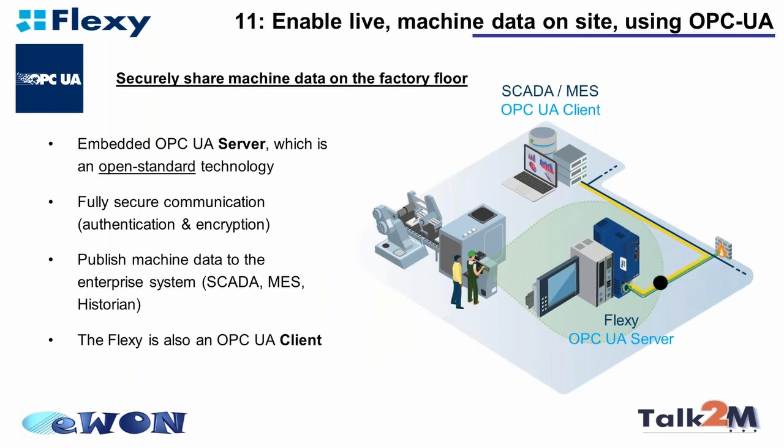On the site itself, the Ewon Flexy can also pass data in real time to SCADA systems. So if you're installing a machine on a site and the machine data is needed to be integrated into the data systems and the SCADAs on that site, the Flexy 205 provides an OPC-UA server. And an OPC-UA server, again, that's a standard. All SCADA systems will be an OPC-UA client.